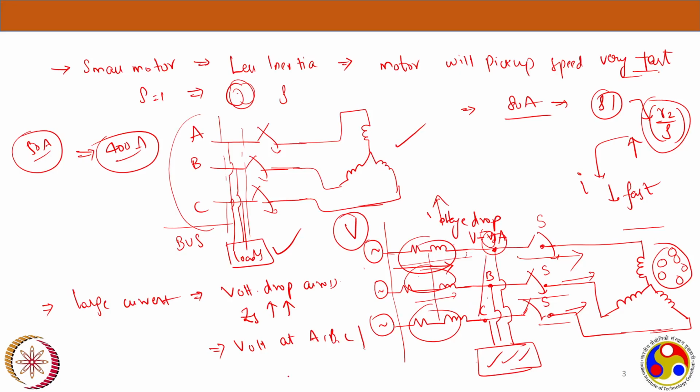With this reduction in the voltage, you will see a voltage dip in the supply, in the input voltage to our appliances. So every time you switch on this induction machine at points ABC, where other consumers are also connected, we will see a dip in the voltage.